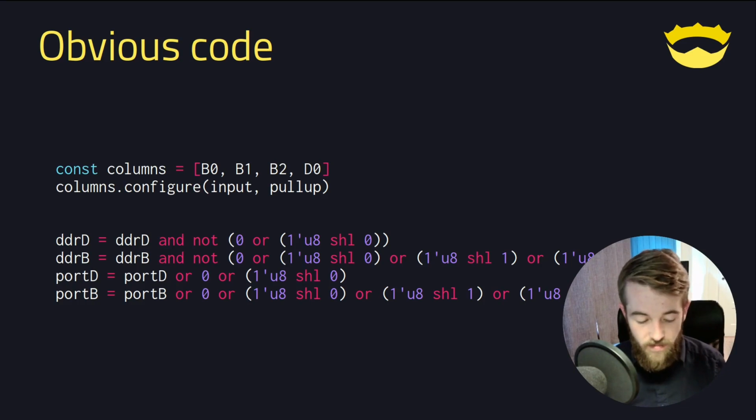This is one of my really strong peeves with the Arduino system, is that pins are numbered, and the pin numbers aren't anywhere on the chip. So you always need to have the reference chart up to see what pin is which number. With this, these are the names that are on the chip. So it's really easy. You pick up the chip, you see there's B0, I write B0 in my code.